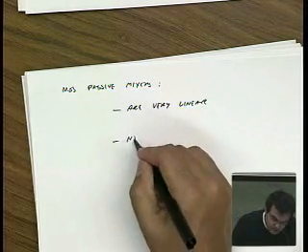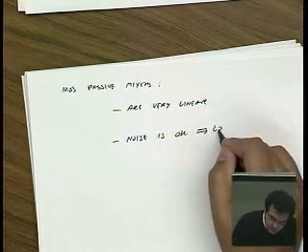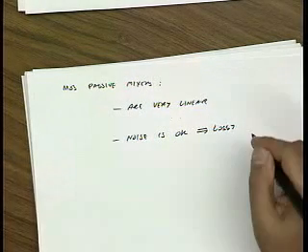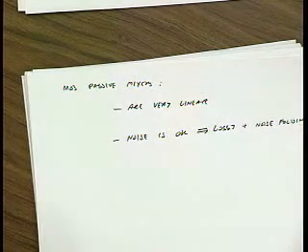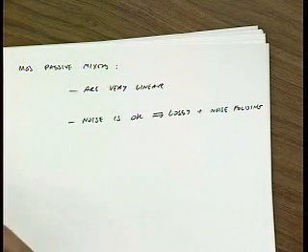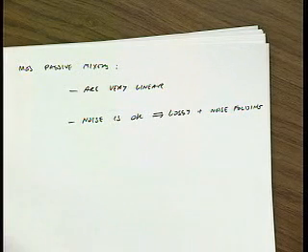The noise is okay. It's lossy. That means the noise figure is going to be at least as large as the attenuation, right? Plus the noise folding. But at the same time, if you think about the intrinsic noise of the device, again, it's a small resistor. So when it's on, it contributes a little bit of resistance, so a little bit of thermal noise. And when it's off, it contributes essentially no noise. Okay. All right, any questions about that?